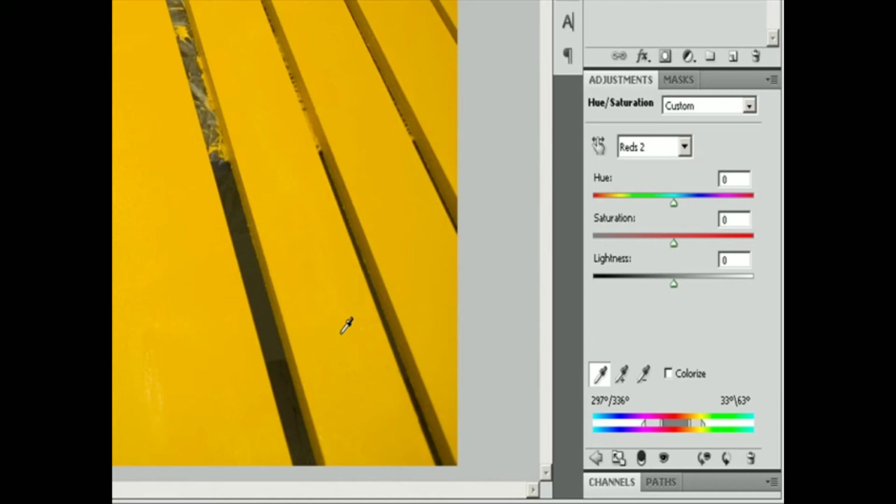Control-drag in Windows or Command-drag in macOS the color bar so that a different color is in the center of the bar. If you modify the adjustment slider so that it falls off into a different color range, the name in the Edit menu changes to reflect this change. For example, if you choose yellow and alter its range so that it falls into the red part of the color bar, the name changes to Red 2. You can convert up to 6 of the individual color ranges to varieties of the same color range, for example, Red through Red 6.